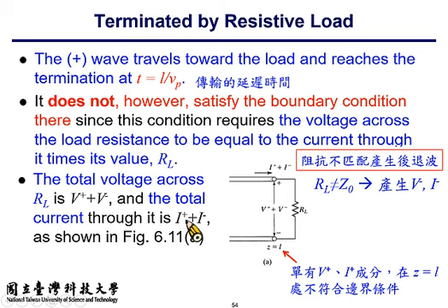So at the moment t equals L over Vp, the I plus and V plus signal will arrive at the right end. However, assuming the characteristic impedance of the line is 50 ohm and the termination is 100 ohm, 50 ohm does not equal 100 ohm, so you have an impedance difference, which means the voltage over current ratios are not consistent on the line and on the resistor.